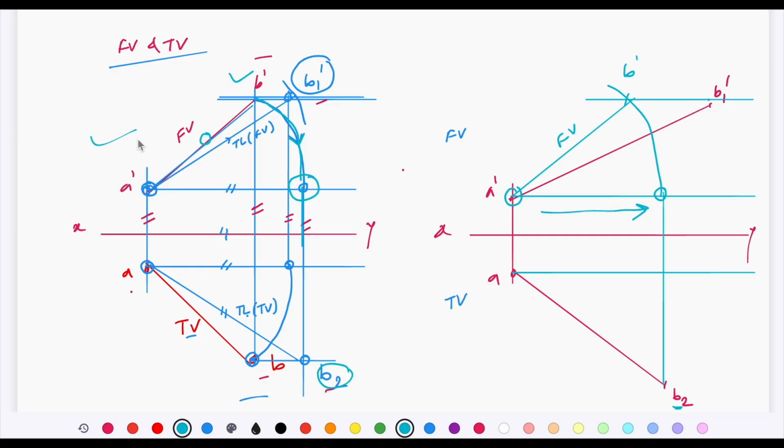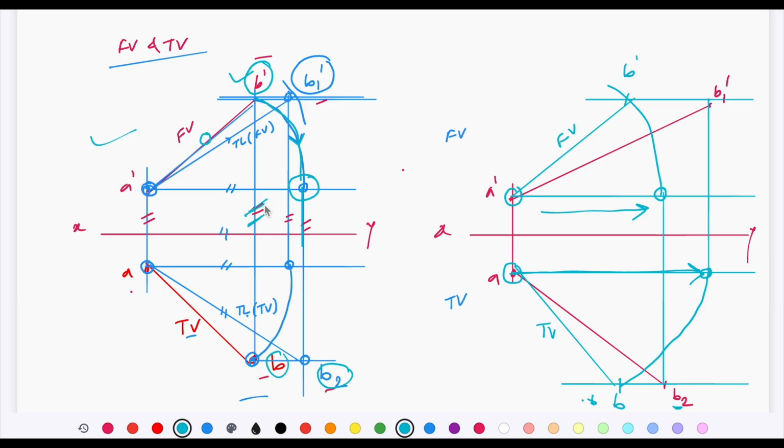Now similar to this case, when you are going to draw top view, that is you are going to look at the point B, again you have two possible choices. The first, similar to what you did with B2, you can project this point vertically downward till the locus of A, keep compass on A, take radius equivalent to this much distance and rotate this point to have intersection with locus of B2 and connect with A. This is going to be your point B and this is top view. You can do this one, or we already know that B dash and B are always going to lie on the same projector. So once you have located B dash, you can simply project this point vertically downward and have this intersection, and you can locate the point B. Both cases are absolutely fine.